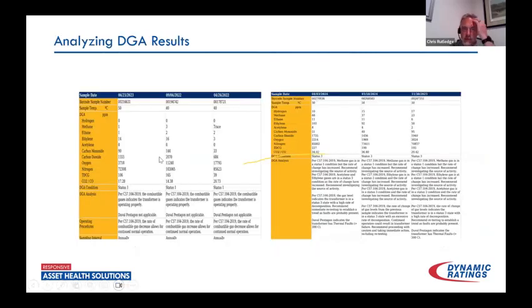So this was a case that just came in. I was looking through that I found really kind of tied everything together pretty nicely, I felt like. So if we look starting in 22, acetylene's at 0 this whole time. We also have hydrogen values at 0. So apparently a really clean transformer.